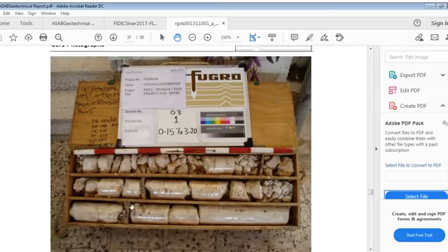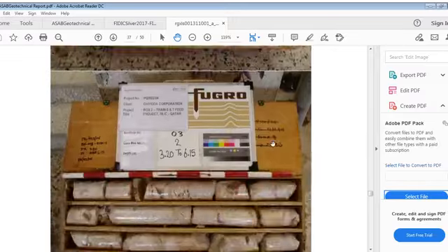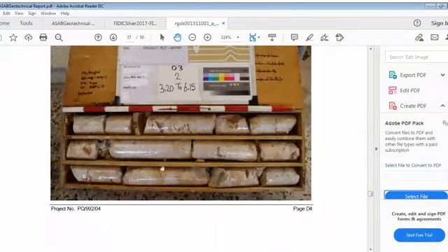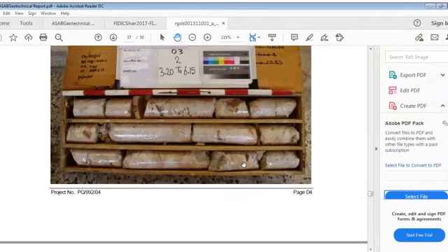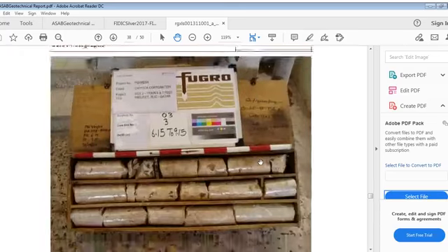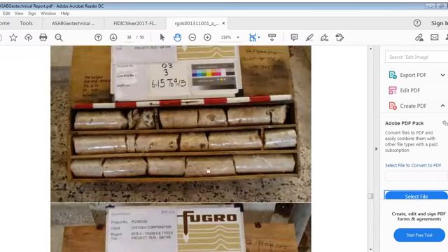Similarly, in this case you will find this piece longer, this piece longer. About 60 to 70% are longer pieces. And here almost all are longer pieces. So RQD is higher in this case than the previous case. You can see almost 90% are longer in such a case.